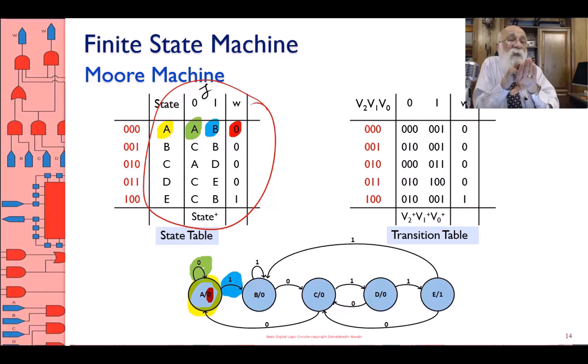Instead of A, put 0, 0, 0. Instead of B, put 0, 1, 0. Instead of C, say 1, 1, 1, or whatever I like. As long as there are unique bit patterns, I'm fine. And then I replace them with ones and zeros.